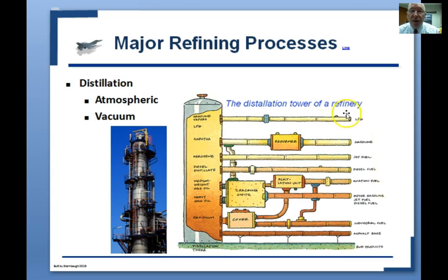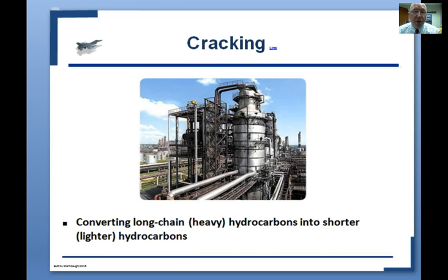So the very top would become the liquid petroleum gases, then the gasoline, and then the middle distillates, and then the heavy stuff down here. And again, this is where the cracking kicks in, and you can see the cracking and the reforming used to make gasoline and some other items as well. I want you to be familiar with the cracking process. You can rewatch that little video, but the main thing I want you to keep in mind is cracking is one of those things that's used to generate higher value products out of a barrel of oil.